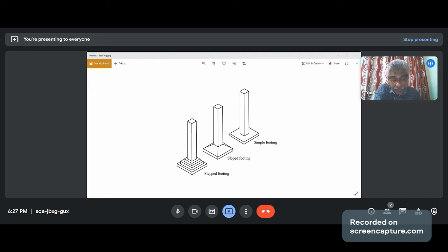The bearing capacity is governed by shear failure criteria, and the next criterion in fixing the bearing capacity is settlement. So we decide the bearing capacity based on shear failure and settlement. You must have studied various values of settlements for various types of soils. These values may vary from 25 mm to maybe 100 mm. Generally we may accept a value of 25 mm or 50 mm, as the case may be.